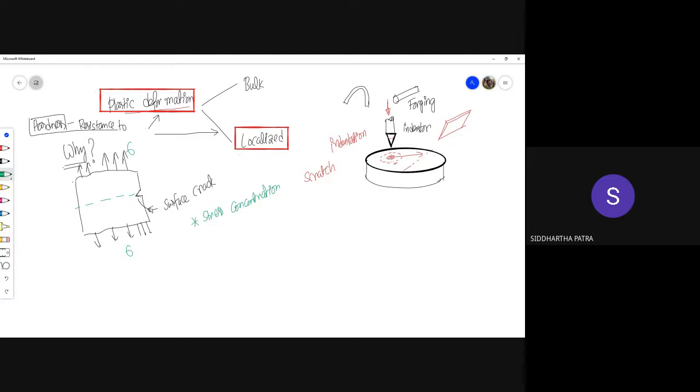Let's look at it. If you are really far from the region of the crack tip, the stress is very nominal. You applied uniform stress, so that uniform stress is more or less the stress state if you are very far away from the crack tip.